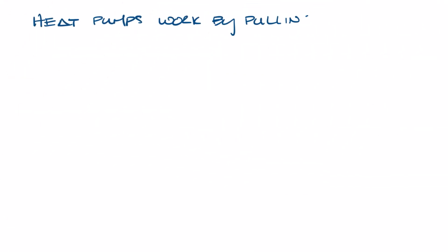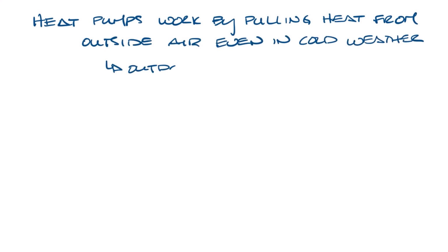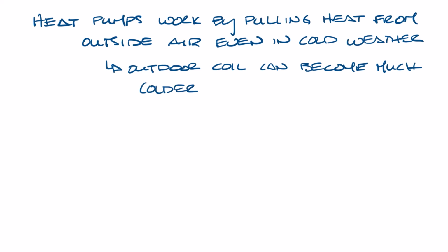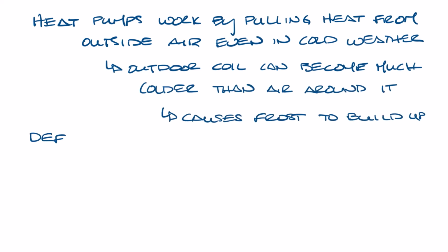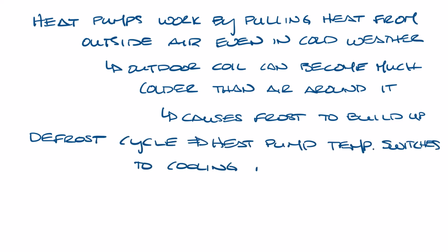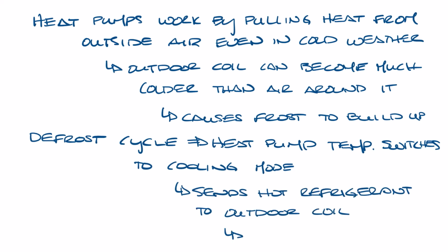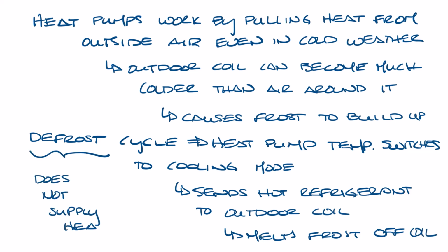So as a reminder, heat pumps work by pulling heat from the outside air, even during cold weather. The outdoor coil can become much colder than the air around it, which causes frost to build up on the coil. During the defrost cycle, the heat pump temporarily switches from heating to cooling mode, which sends the hot refrigerant to the outdoor coil to melt the frost off the coils. So during defrost cycle, the heat pump is not supplying any heat to the space. That brings us to full defrost and net zero defrost systems. Let's slide this over and talk about them.